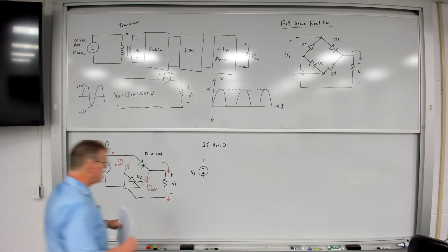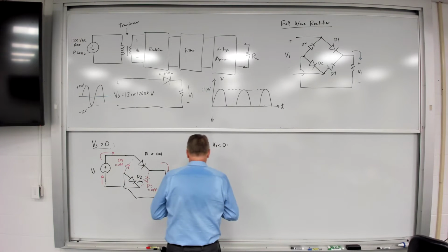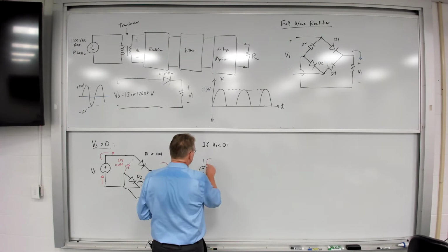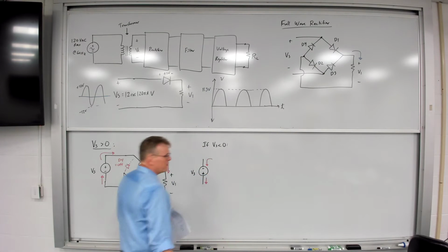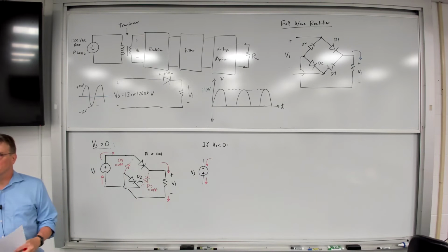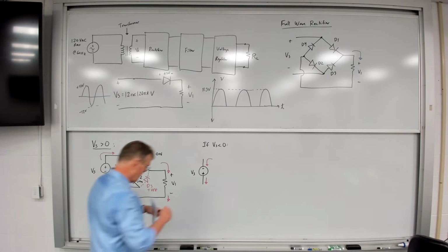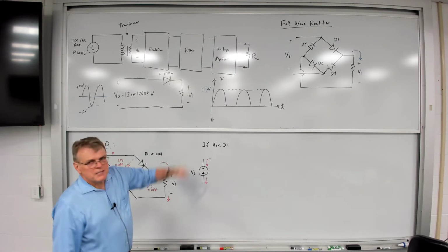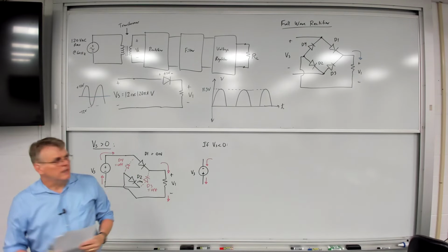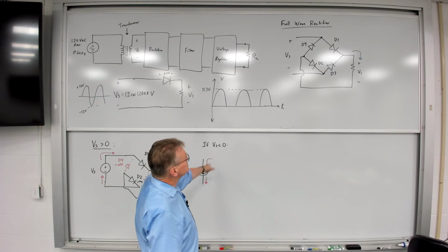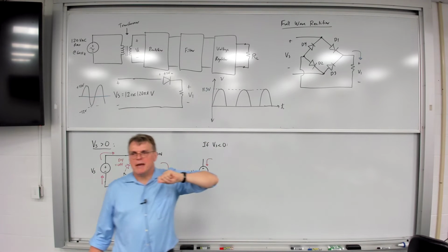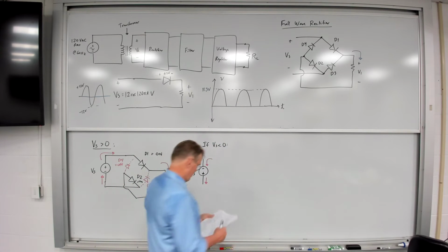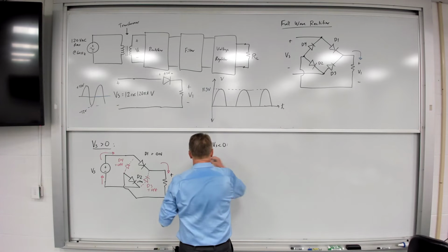And so in this case, current is going to flow into the negative end and out the positive end. So the direction of current, the flow of current is reversed. And in this case, we can look at this and very quickly prove to ourselves that if the current's going in this direction, the only possible path that the current can now take is through D3 and D4. So in this case, I now have this.